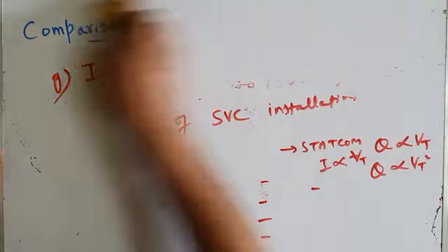So therefore, where cost is the main factor, like poor states in India, which cannot afford large costs of STATCOM, because presently the cost of STATCOM is higher than cost of SVC. So if you have to make a choice between the two, if cost is the consideration, then you will definitely go in favor of SVC.